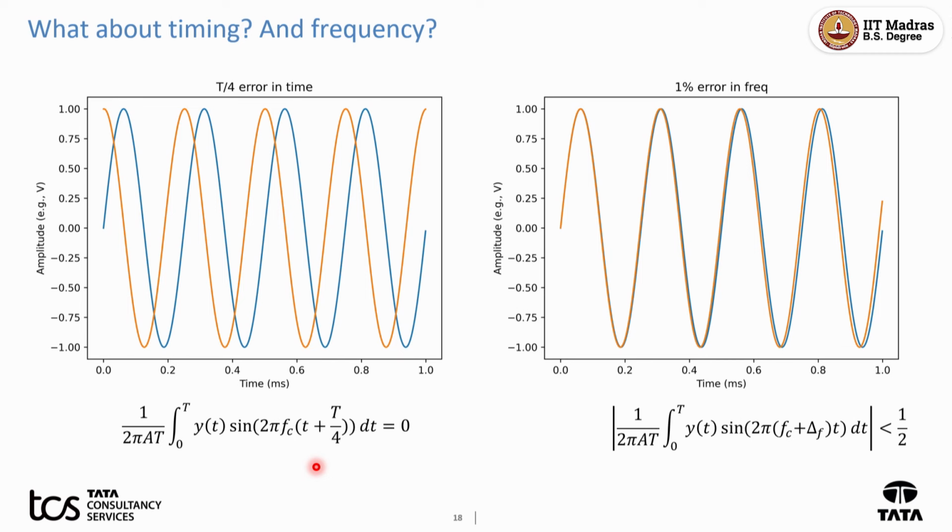So, all communication standards prescribe a limit. We will be guaranteed that the tower will not do worse than 0.1 parts per million. That is the requirement. That means, if the frequency is 1 million hertz, actual frequency can be up to 1 million plus 0.1 and 1 million minus 0.1, whatever that is. That still does not mean it is 1 million. That is the range that the phone has to know. Within this range, I should still be able to correct that frequency.